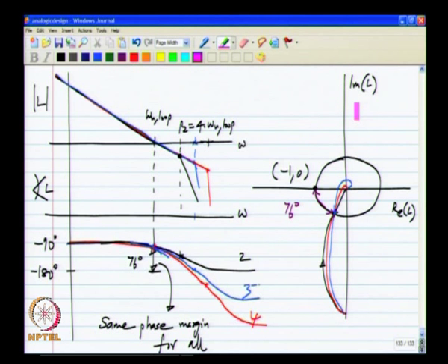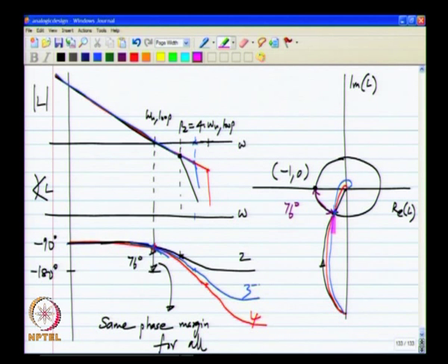So, the ultimate test of stability is the Nyquist plot, because the condition of poles being in the left half plane can be mapped to the Nyquist plot not encircling the -1 point in the clockwise direction. But assuming that the magnitude is well behaved, that is the magnitude reduces monotonically, then it goes inside.